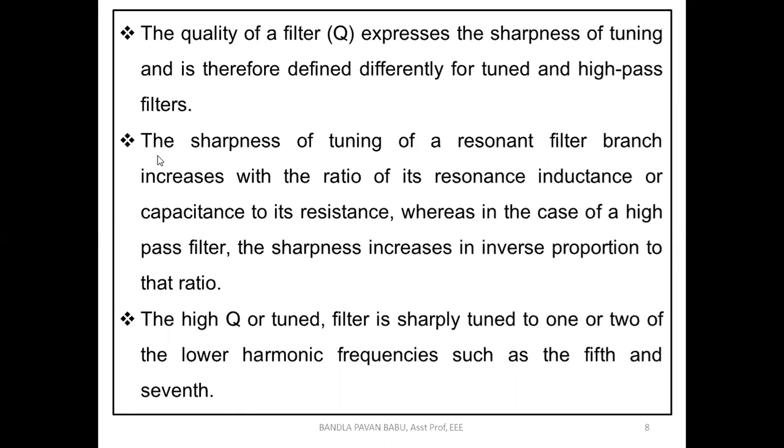Okay, next, the sharpness of tuning of a resonant filter branch increases with the ratio of its resonance inductance or capacitance to its resistance. Whereas in the case of high pass filters, the sharpness increases in inverse proportion to the ratio.